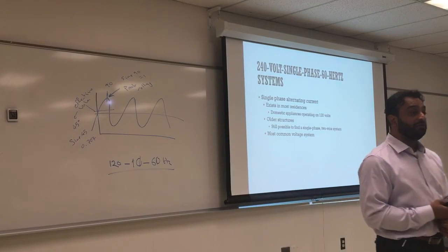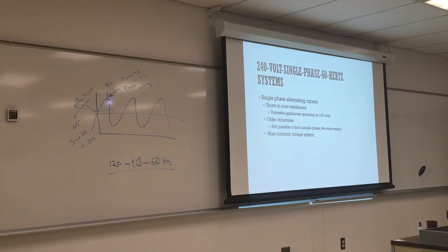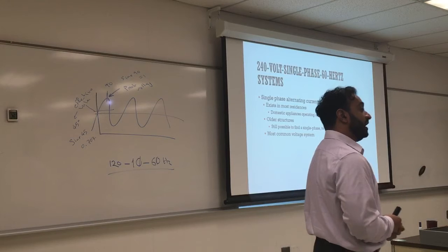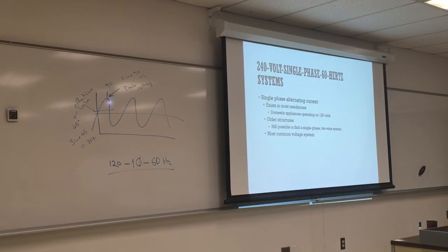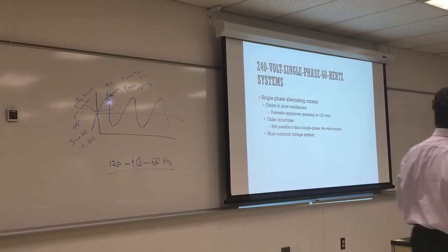If you feel in doubt and feel the wiring is not sound enough to handle your equipment, you might ask the owner to change the wires because it's unsafe. How do you know if the installation is safe? The wire usually is not going to have any problems. The installation could be crispy, falling apart, some parts are exposed. If you see any part exposed, definitely you have to change the wires.